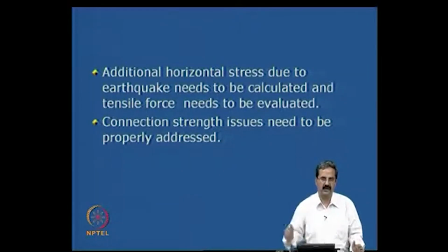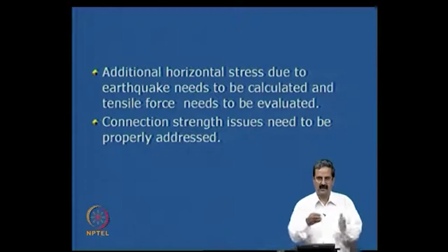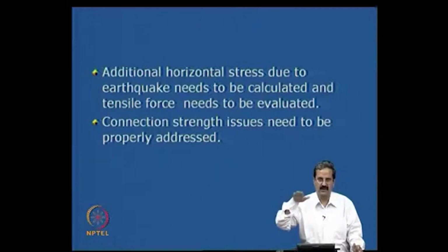like, I saw a case, close to Bangalore, where a long time back the connection was so weak that it came out, and all the facing panels just came out. They are all on the ground. So that's a very poor situation. The reinforced soil, the geogrids are all intact, but since the connection was not good, it couldn't hold the facing weight. All the facings came out, and people had to rehabilitate that whole RE wall using soil nailing.